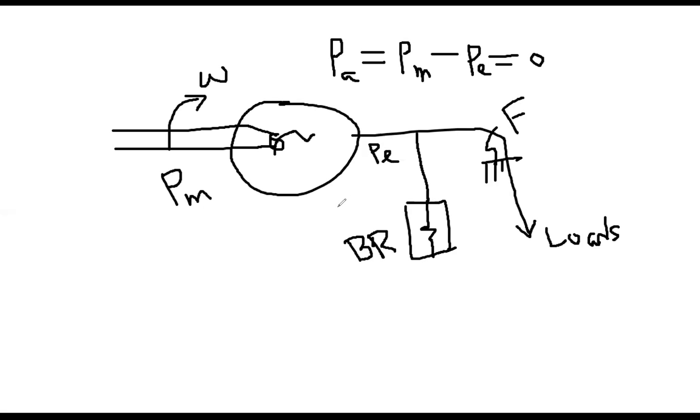So now, look, we are controlling this braking resistor with the help of the firing angle alpha. Assume there is a thyristor circuit here. What is our goal? During a fault, because Pe goes very low, close to 0, you support it with the help of the braking resistor, meaning you try to increase Pe from 0 to maintain stability.